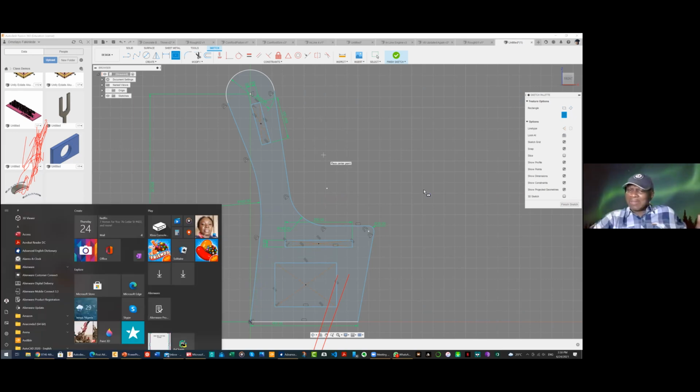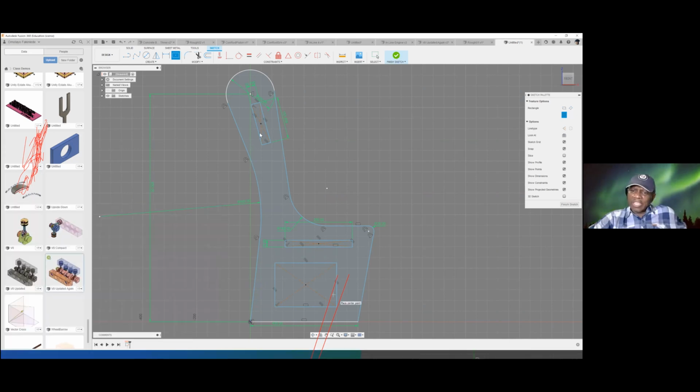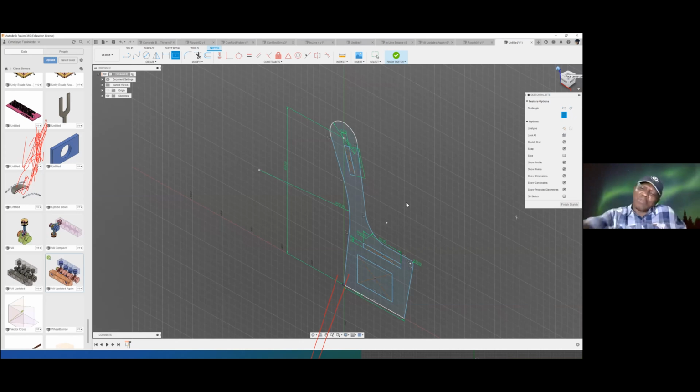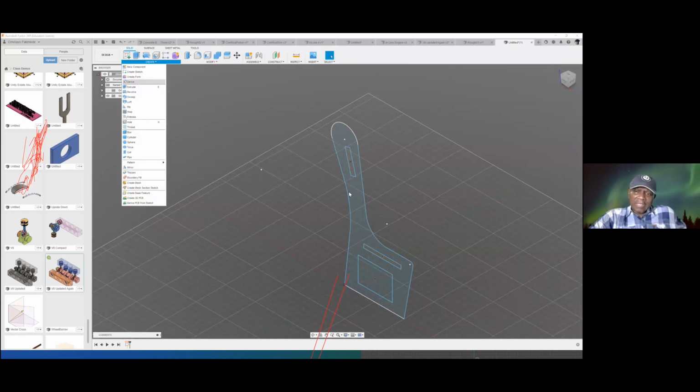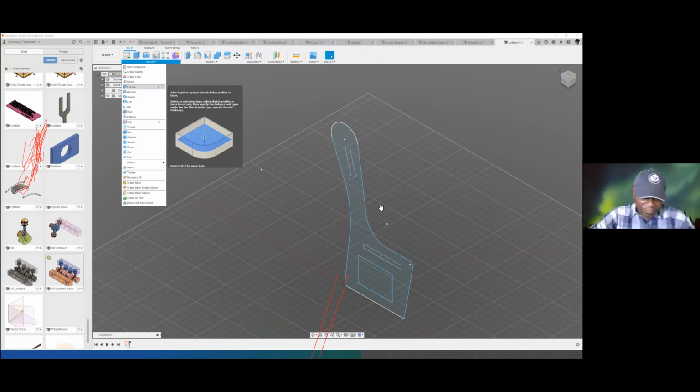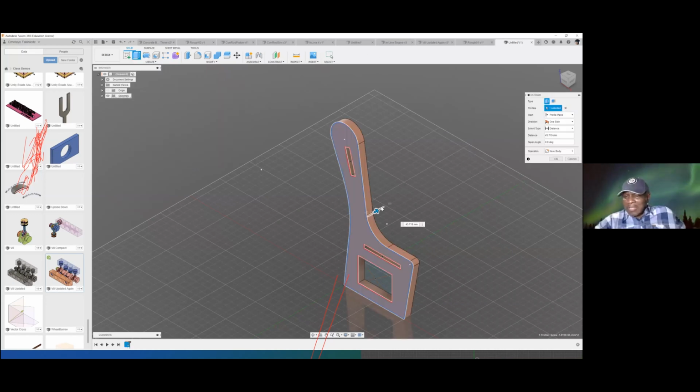Now we can go home, and we can say okay, and finish sketch. So this is the sketch. This is enough to make our armrest, and it doesn't take more than 5 more minutes to make the whole bench. Now, for instance, you can create an arm by creating an extrusion. If I create an extrusion and I extrude this for some distance, let us say I extrude it through 75. That is that. If that is too thick, I make it thinner.